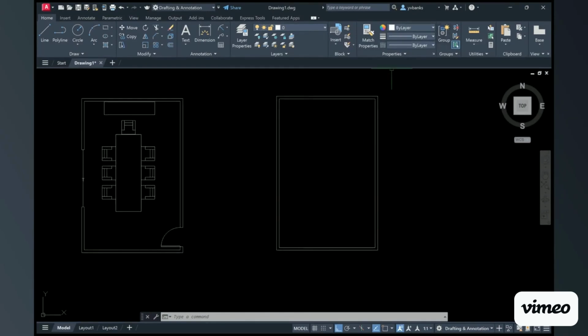From here, we can double check our measurements by using our quick measure tool. The exterior line should be 16 feet and the wall should be 24 on the outside. Inside is 15 feet 2 inches by 23 feet 2 inches.